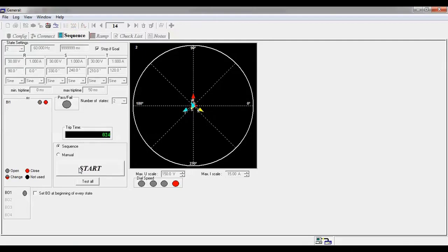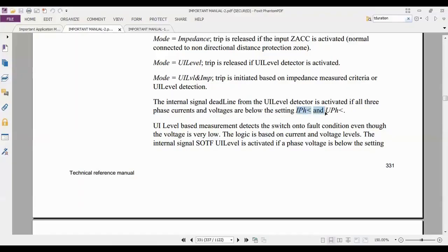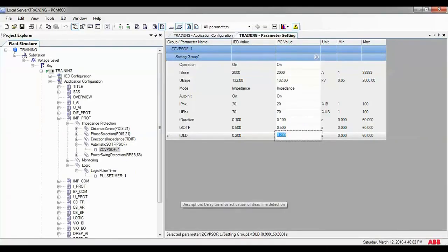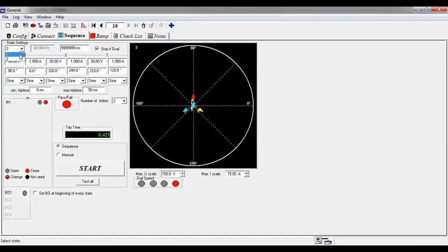And of course, we can try to make this first page larger than 500, but let's play around with the emergency. For example, make it less than 0.2, like 0.19, so both are less. You have violated one of the conditions, meaning if you only set the current as the highest, then it's no longer DD, because for DD, both need to be less. So you violated one of them, and it's no longer DD, so it falls under zone 2. But if you set both below their settings, then it was DD, and it falls under another condition.